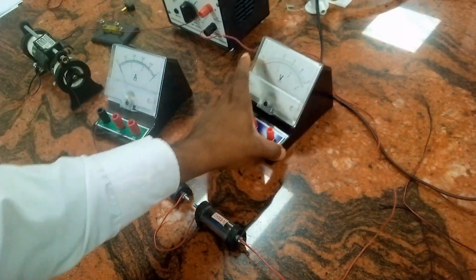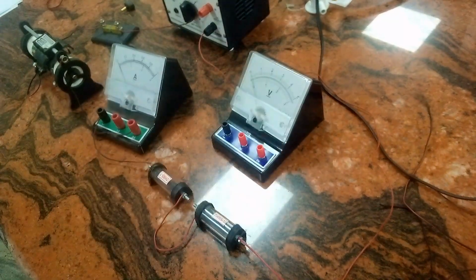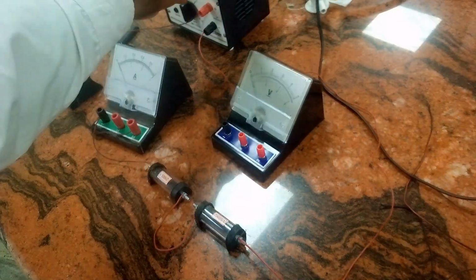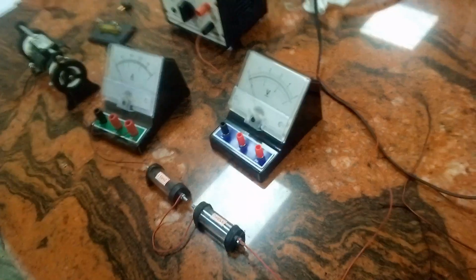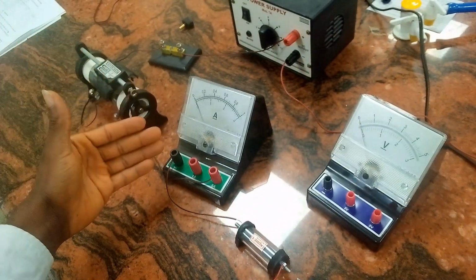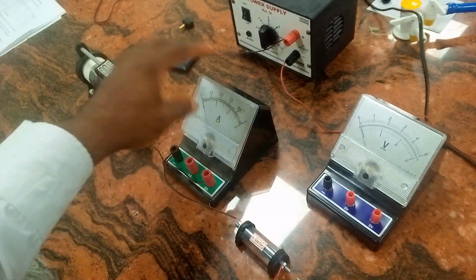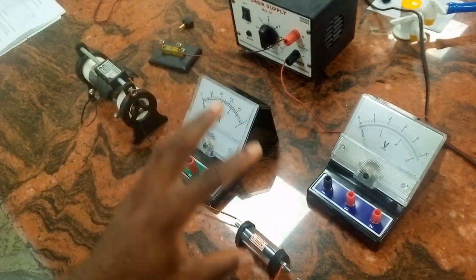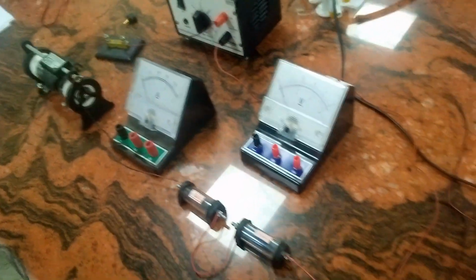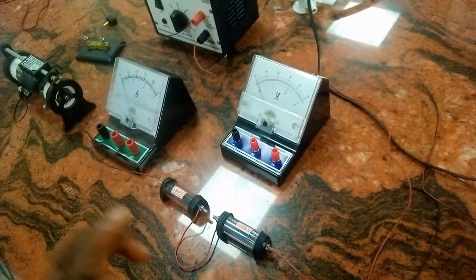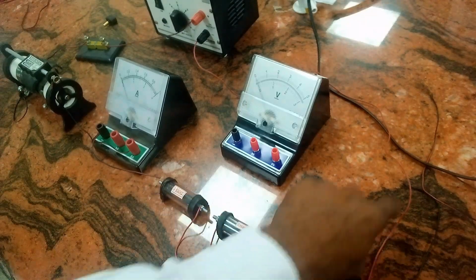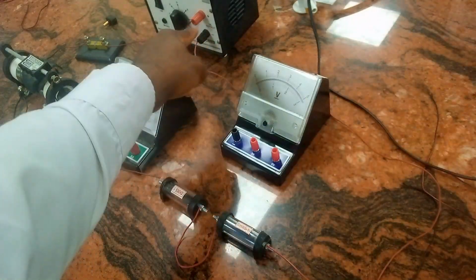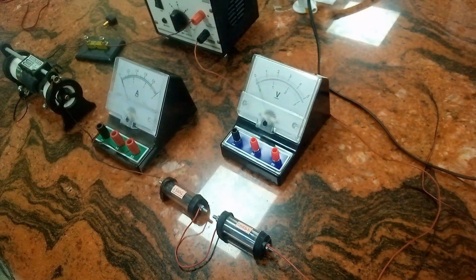So by doing this, we have been able to make our connections from the supply to the key, then from the key to the rheostat, then from our rheostat we connected it in series to our ammeter. Then from the ammeter, we made a connection in series to our 1 ohm resistors. So this is our standard resistor. Then from there, we ensured we make a straight connection back into the negative terminal.